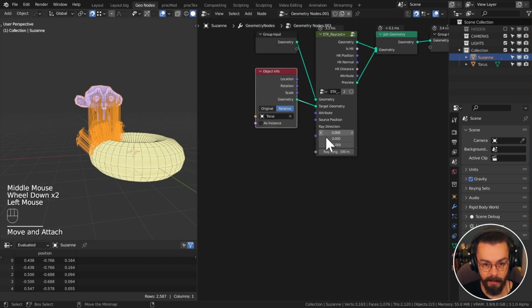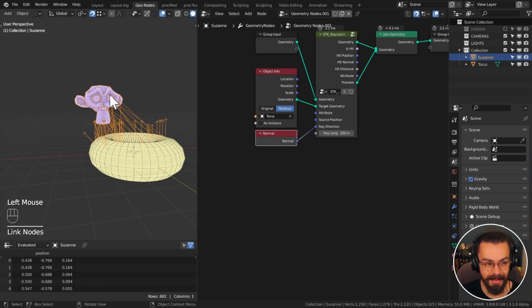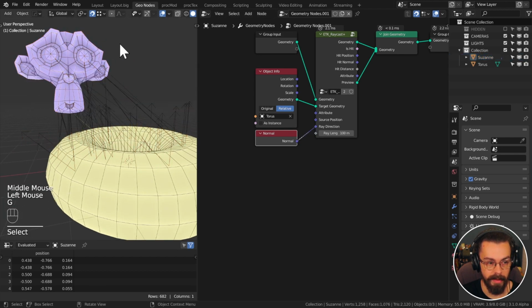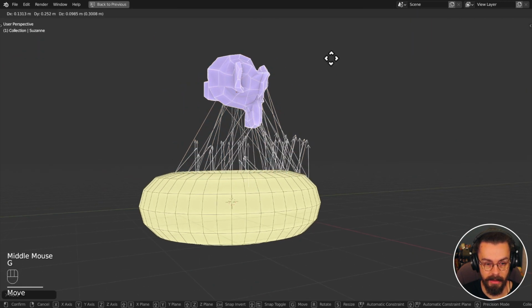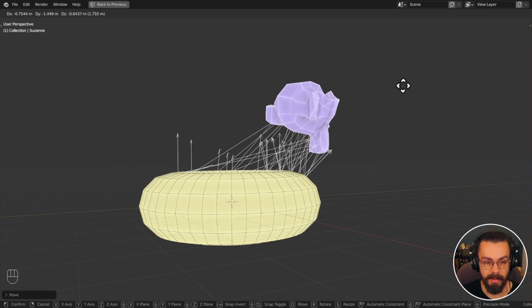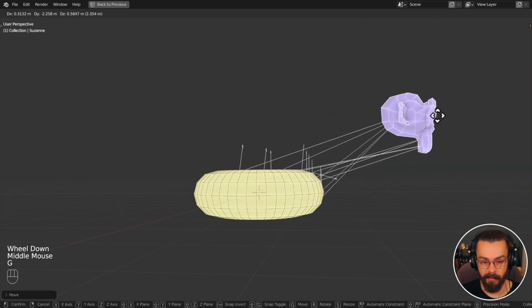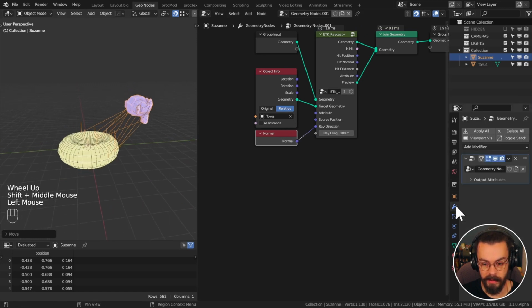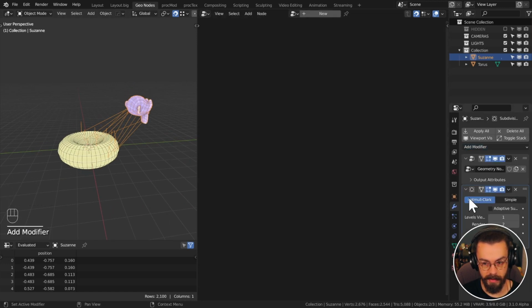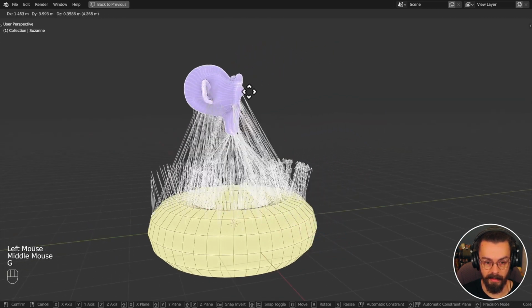So that's awesome. And we can still plug everything in, like we could manipulate the source position, or we could set a ray direction. So maybe we set the ray direction to this surface normal instead. So now Suzanne is actually shooting out in all directions from her surfaces, and we can see each of those rays where they hit our torus and the direction of the normal at that position. So it's just a really nice way for us to work. And anywhere that we do not have a hit, it just doesn't draw anything. So there we go. And this is dependent on the points. So if I was to add a subdivision surface to her just before in here, then you're going to see that we're getting more points because it's basing it entirely on the number of vertices.